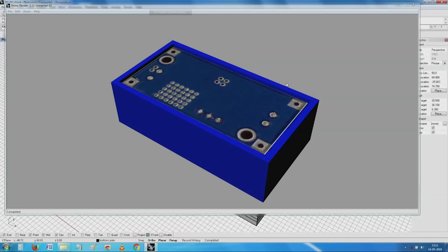Now, one more item I have intentionally left off for you is, do I now put a heat sink on top of it? Yes. Remember the whole thing inside. Now, I have these 4 connections here. I have to decide whether I give a relief on the heat sink, and then I have these 2 mounting holes. This is where the via holes are, and the manufacturer has recommended that we use the via holes, put a little bit of heat sink paste and just clamp it down with sufficient force.